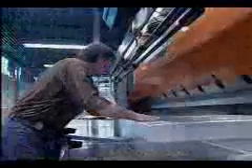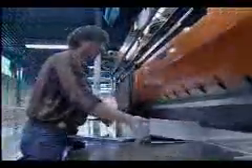Location or distance guarding refers to positioning the hazardous parts of the machine so they are inaccessible or do not pose a threat during normal operation. The position of operation controls is an example of location guards. Two-handed trips require the operator to place both hands on the trip, ensuring their hands are a safe distance from the hazard during operation. It is important to conduct a thorough hazard analysis prior to safeguarding by location.